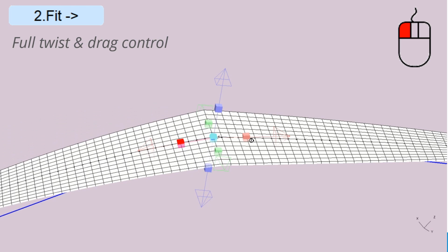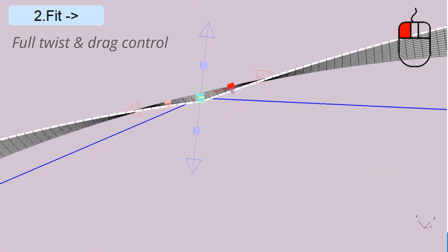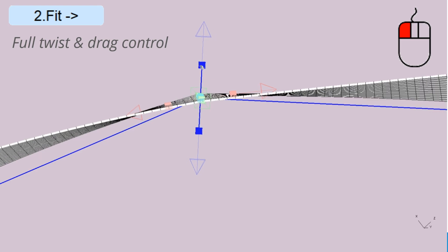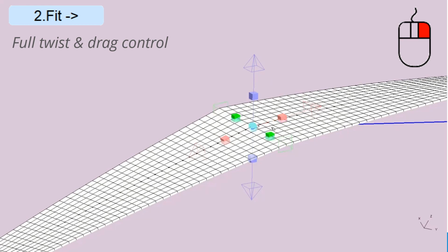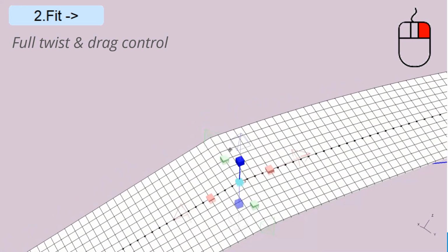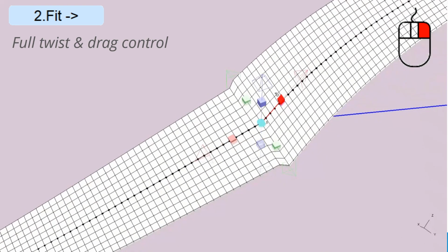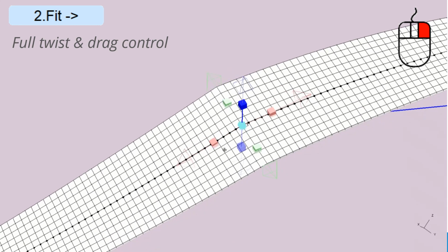Red cubes break the spline and can give us a sharp change in direction independent of the other side. Right-clicking on these cube handles skews the belt in each local direction. The center of rotation is the original path point, so I recommend using zero projection when setting up the belt path.